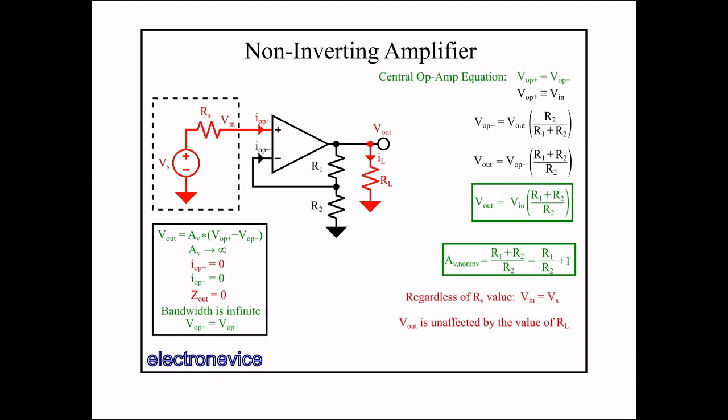So here we see that by adding a simple resistive divider, feeding back from the output of our infinite gain op-amp, we are able to set the gain to a finite value tailored to our application by setting the values of R1 and R2. This is a very common use for op-amps, and a simple way to get a precise, well-defined gain.